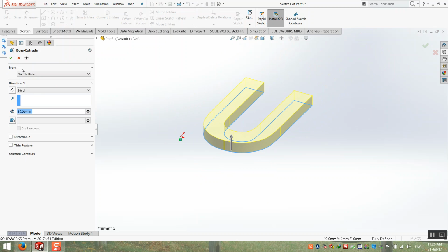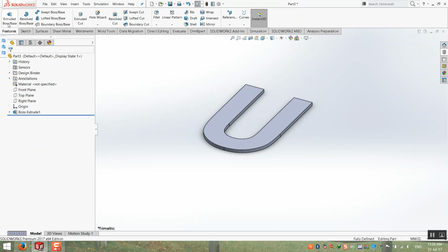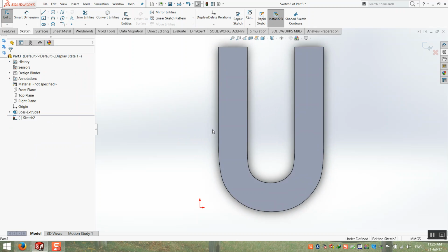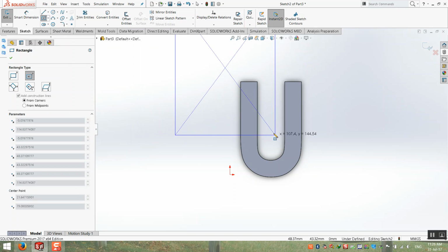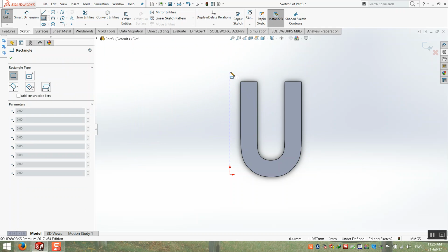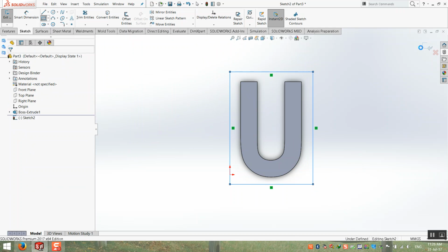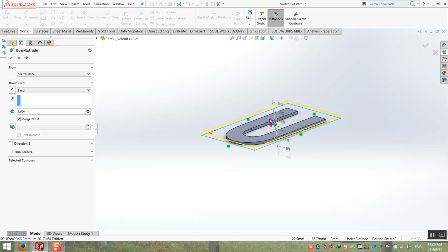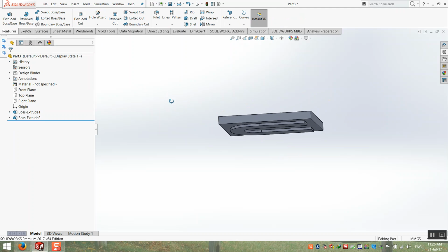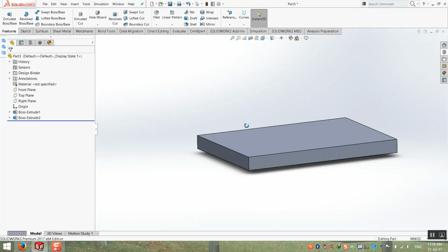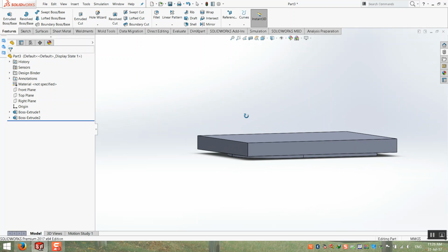For example, you have this extrude that will act as the depth that you need in sheet metal. I need 3 millimeters only. And create. This will be a punch. You see? Nolly, understand the idea?